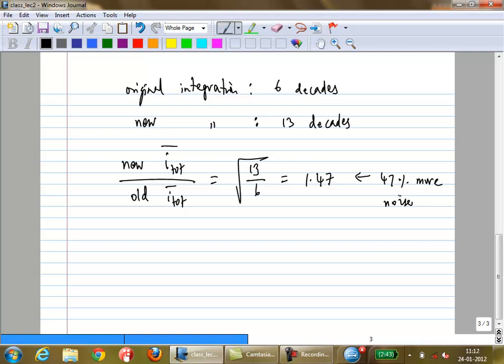Take a simple RC. So let's say you have a DC coupling, AC coupling cap, right? In reality, in a real system, the output side will eventually settle to the DC that is set by something else on the right side. But in reality, if you really want to settle to the DC, you'll have to wait for infinite time. It's an exponential, remember. Any settling phenomenon is an exponential. So if you really want to observe the DC, what you can say is that compared to your time constant which you are interested in, your observation time is large enough such that you can assume it's DC and move on. Okay? That much you can say.